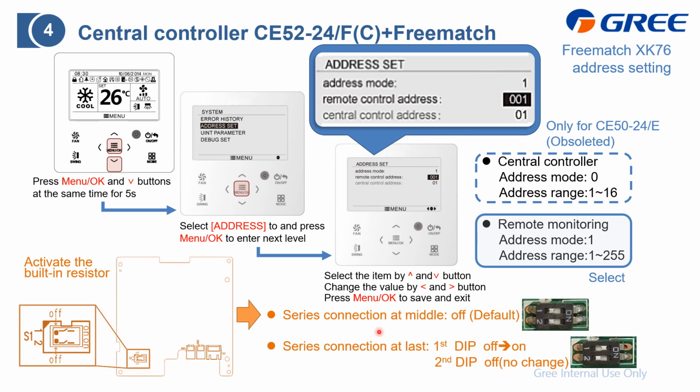And after that, just at the back of this wired controller, if this one is located at the last, don't forget to turn on the built-in resistor to ensure the communication.